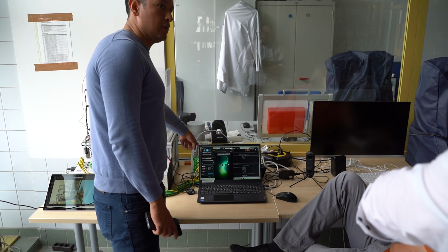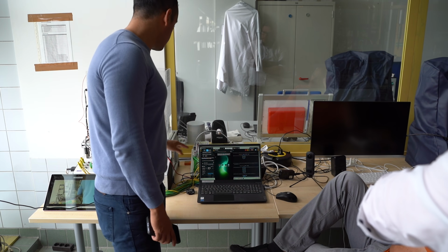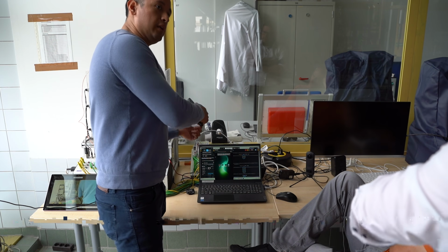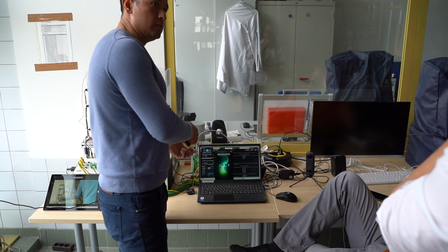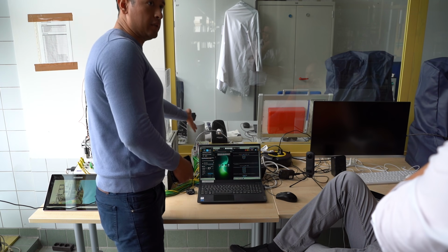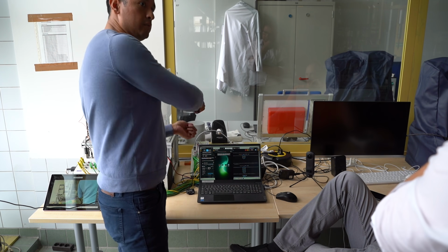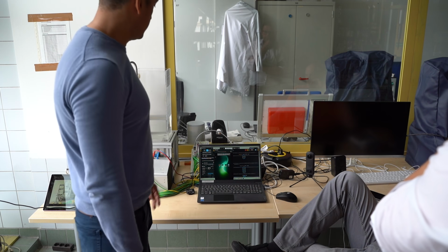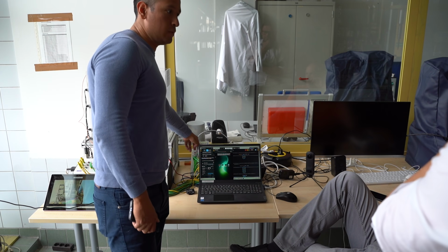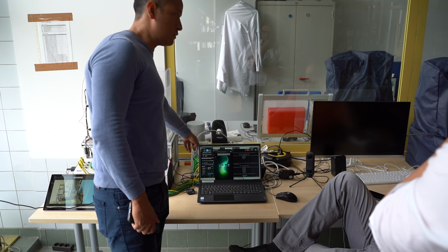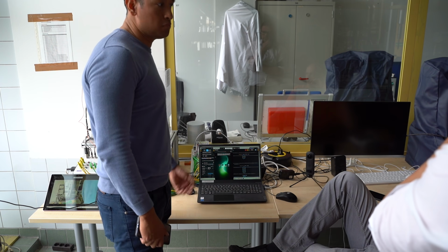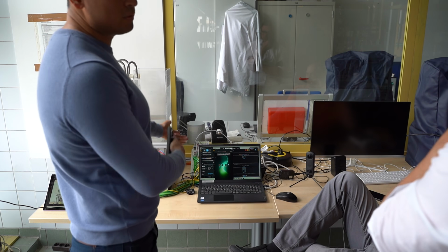Maybe it's not the system that is failing, maybe it's the card in here that is not sending directly anymore. So you have to check if it's working. It's normal practice, so we can maybe put something in there that says there's a fault, check. And here we know already that it's a 24 volt power input. So it's just a matter, if you want it, we can add it.